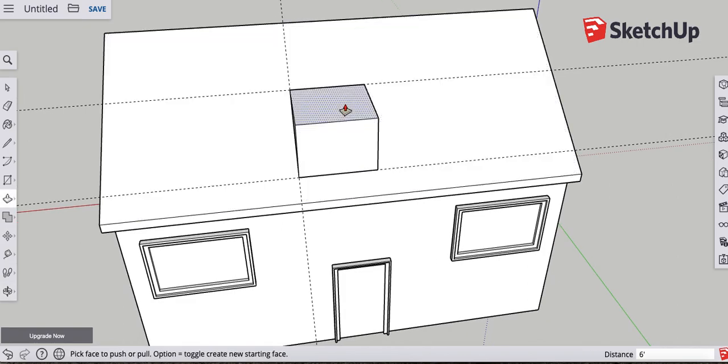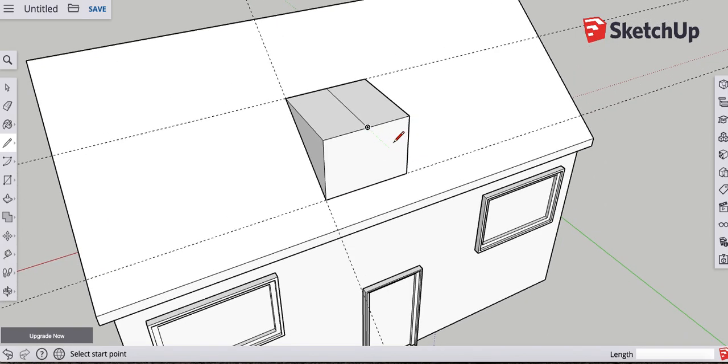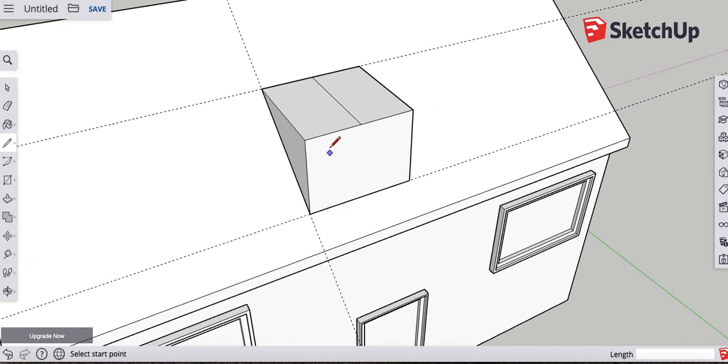Okay, now what we'll do is we'll draw the roof. So I'm going to draw a line going this way. Line. Midpoint. Just hover over the midpoint. Click. And click. Okay, now just like I did with the original roof, I am going to press move, actually first, sorry, select the line, then press move.